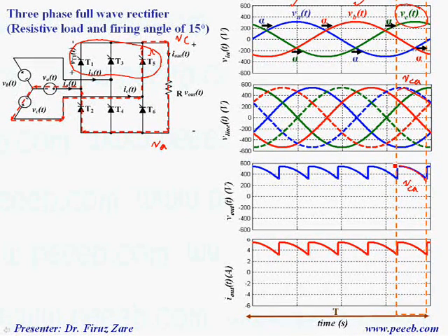The point is that if we look at the top thyristors and bottom thyristors, in the top group and the bottom group, each thyristor conducts for T over 3, and because we subtract this terminal voltage from this voltage, we have line voltage across the load.